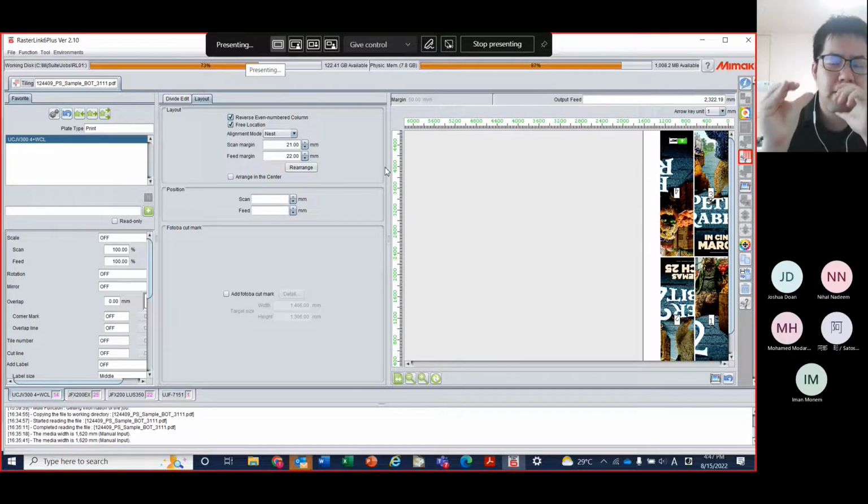The reason is because if you print full size on an eco-solvent printer, it's happening mostly for eco-solvent printers and less for UV LED printers. Because an eco-solvent or latex printer has a heater element on the print pattern and dryer pattern, and the heat across the pattern is a little different, up to 5 to 8 degrees.